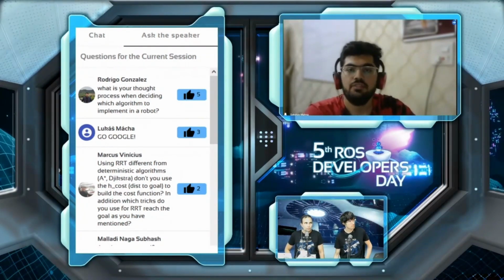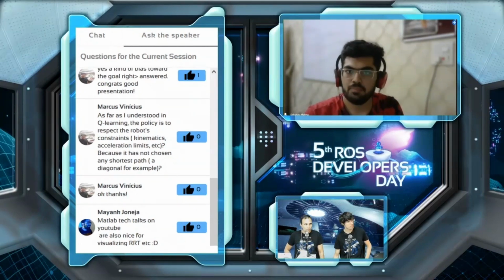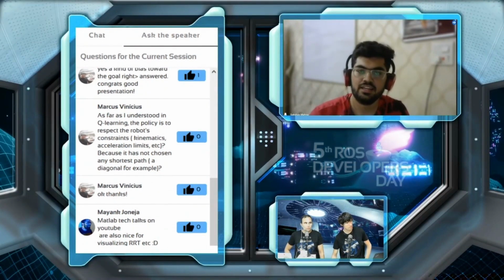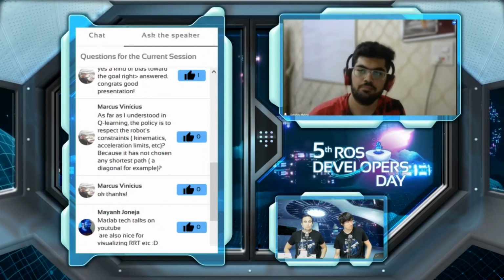In ROS1, as I discussed before, we used a base parent planner plugin that we inherited, and we created our C++ code. There is a very similar kind of thing in ROS2 as well, where we can create our own path planning plugins in C++. There is a little bit of difference in what the function names are and how we do things, but the process would remain almost the same.